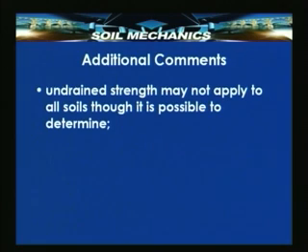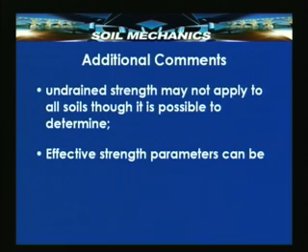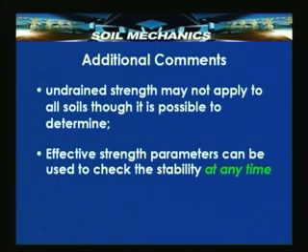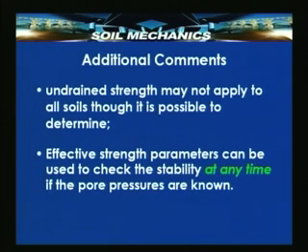We have mentioned some time back that undrained strength are usually determined only for clayey soils which are low in permeability, but actually in principle undrained strength can be determined for all soils, but they may not apply to sands, they may not apply to all the soils, though it is possible to determine that. What would apply perhaps to highly pervious soils like sands and gravels would be only the drained strength. So, effective strength parameters can be used to check the stability at any time if the pore pressures are known.